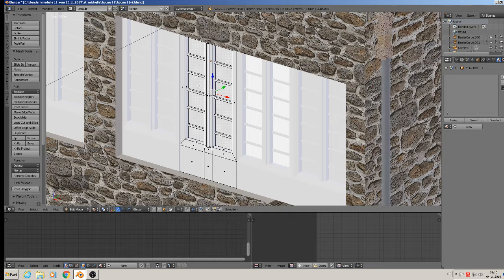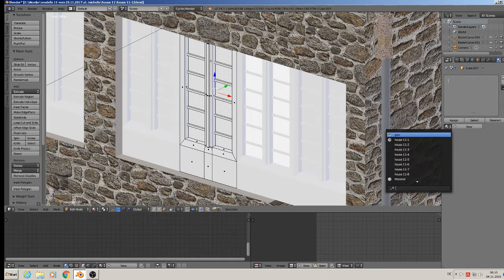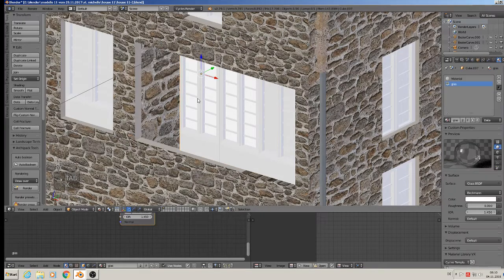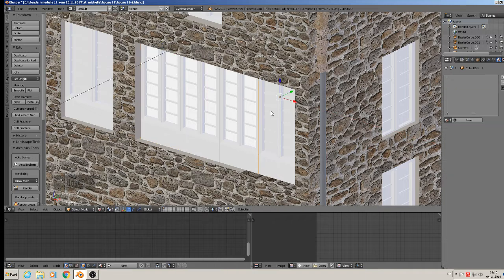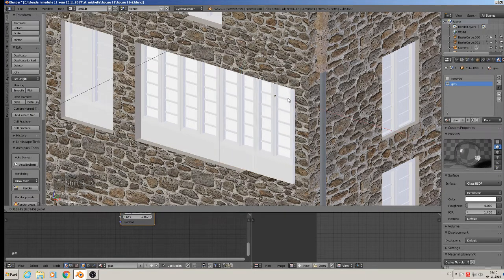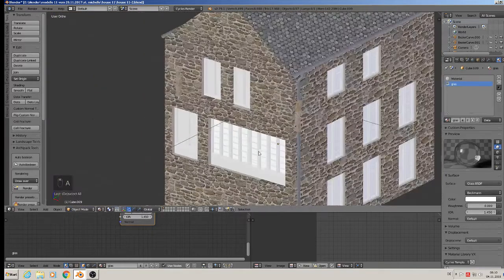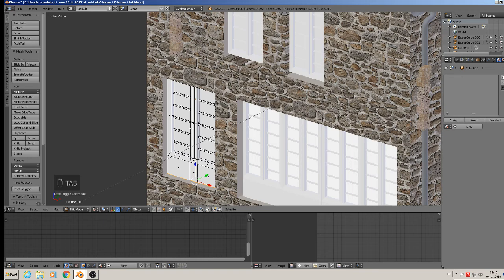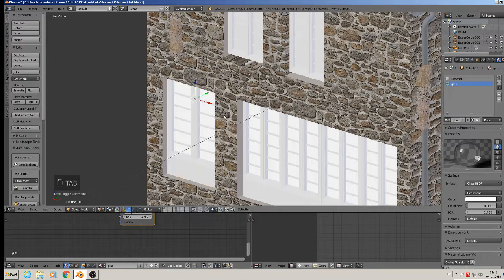You can simply click here on the glass and then press L to select that object, and then you can take the glass itself. But be careful, each one needs the material first, and then plus, and then the glass, and then you can assign that. We delete that here, that is too much, so Shift D and simply copy that. Better, when you don't copy with Shift D but with Alt D, then it takes all those materials with it. Plus, take glass, assign, good.